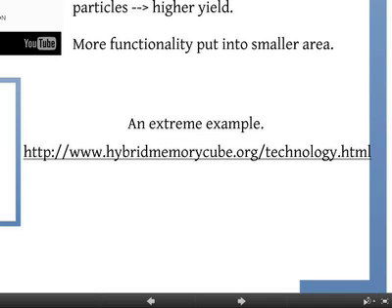So this is something you have to deal with fairly carefully because, of course, if you get really hot, you can destroy the device. It'll slow things down. Remember, when things get hot, the mobility of the electron goes down, if you remember. It's like T raised to minus 3 over 2 or something like that.